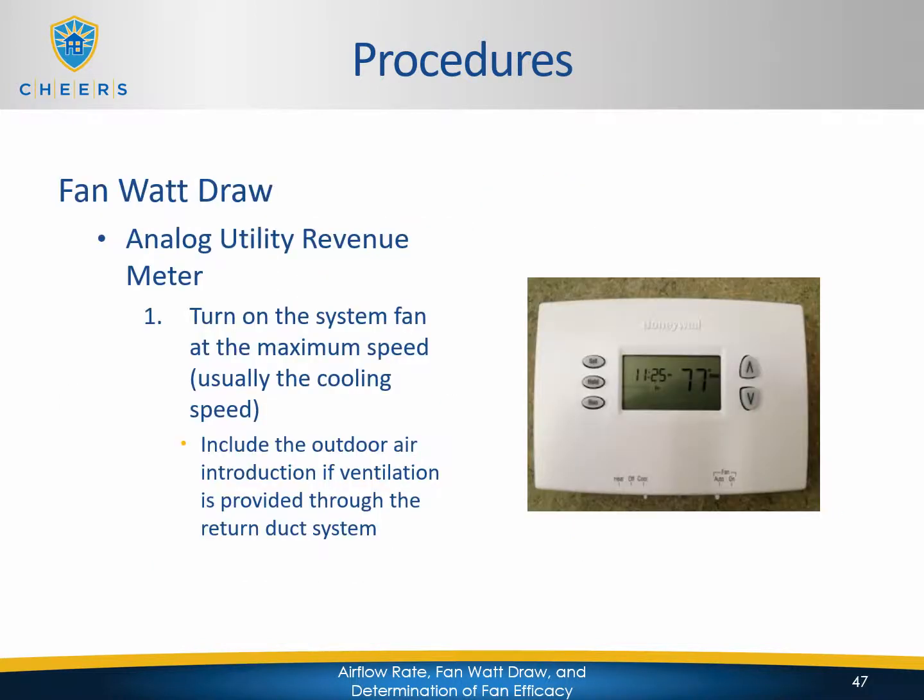Again, you'll turn on the system fan at the maximum speed, which is the cooling speed, like we talked about plenty of times before. And again, include the outdoor air introduction if the ventilation is provided through the return duct system.